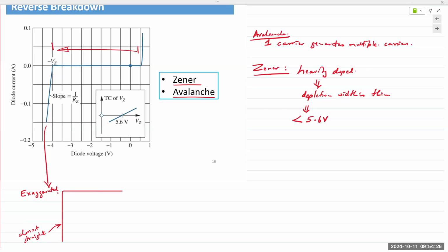I believe the 4001 can withstand up to 50 volts in reverse bias. And then 4002 is a little bit higher, 3 is higher than that, going all the way up to 4007, which I believe can withstand up to 400 volts. You could take one of those diodes and stick it in the wall outlet, and it'll still work fine because the inverse voltage capability is very large.